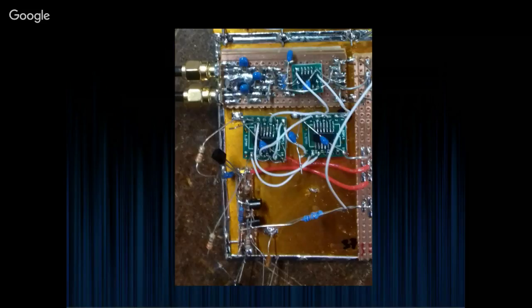As soon as you start trying to use analog bilateral switches, which is what I did, thinking this is how you do it, there's a propagation delay on the activation of bilateral switches, and it turned out to be not fast enough. It's cheaper, easier and lower impedance to just chuck a few transistors in. So although this talk is on digital logic, this is actually the better solution, despite it looking rather messy.